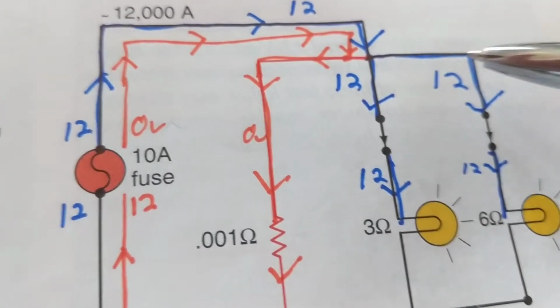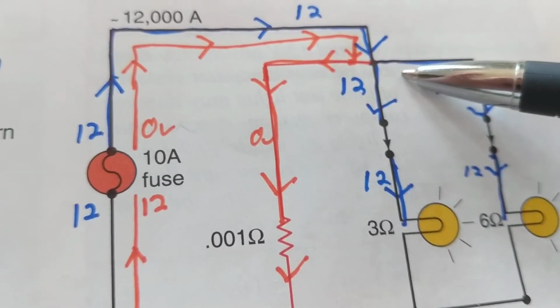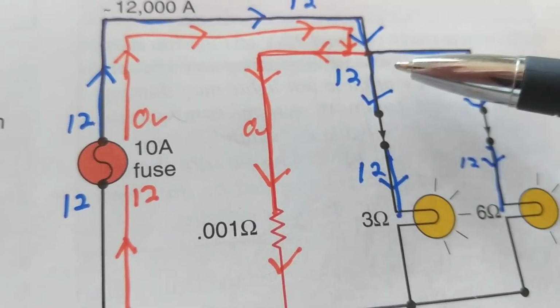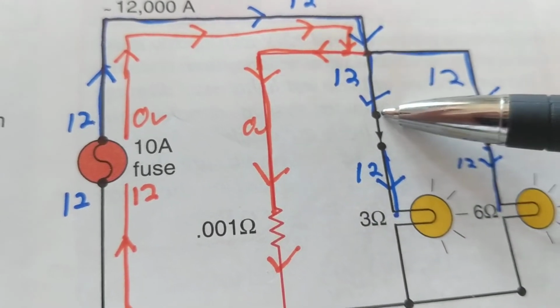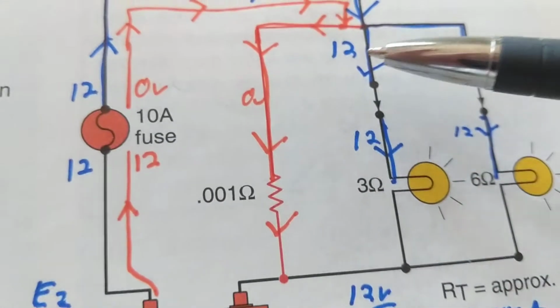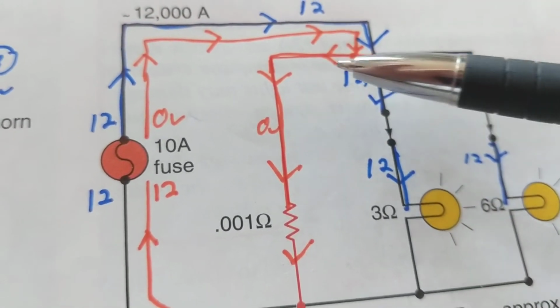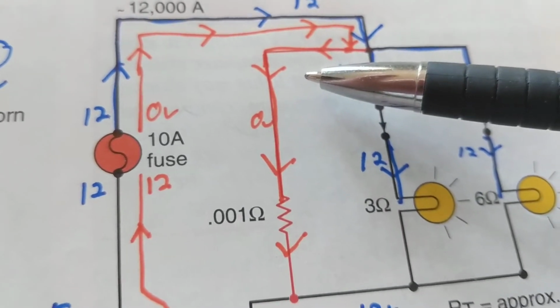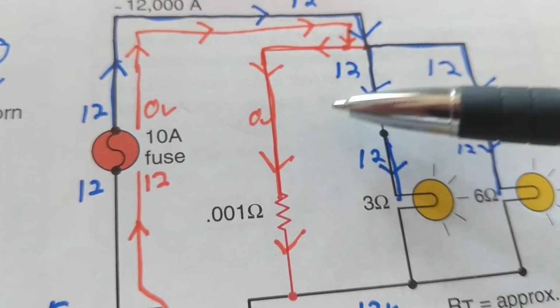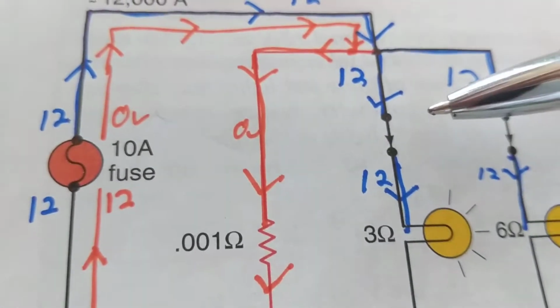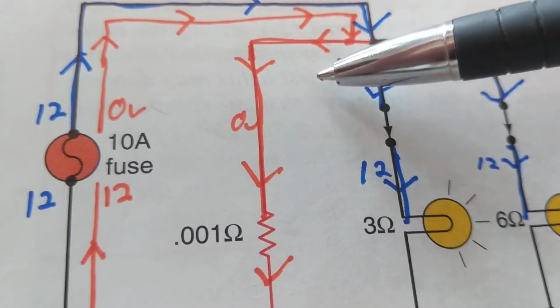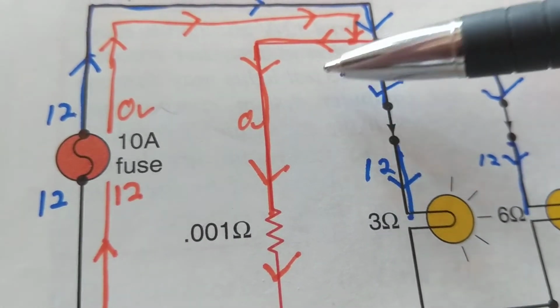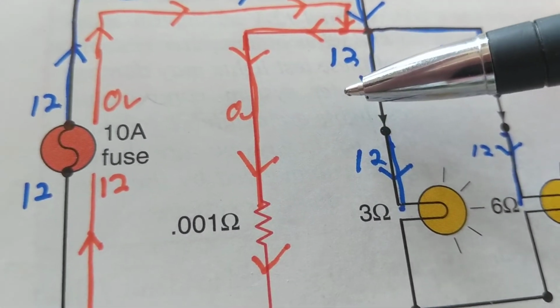If it's 4.5 volts, the computer looks at 4.5, 4.6, 4.7, 4.8. You have to adjust it accurately. You can't just adjust it. If you need 0.4 volts, you can't adjust it to 0.6 and say, well, that's close enough. No. The computer looks at 1/10th, 1/100th of a volt. It'll make a difference to the air-fuel ratio.